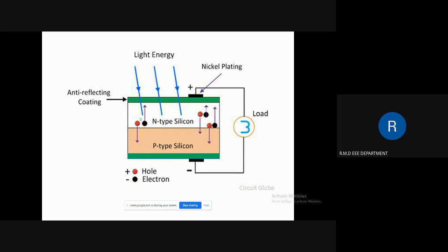So what is the photovoltaic effect? It is a process which generates voltage or electric current in a photovoltaic cell when it is exposed to sunlight. Solar cells are composed of two different types of semiconductors, a p-type and an n-type, joined together to create a p-n junction. By joining these two types of semiconductor, an electric field is formed in the region of the junction.